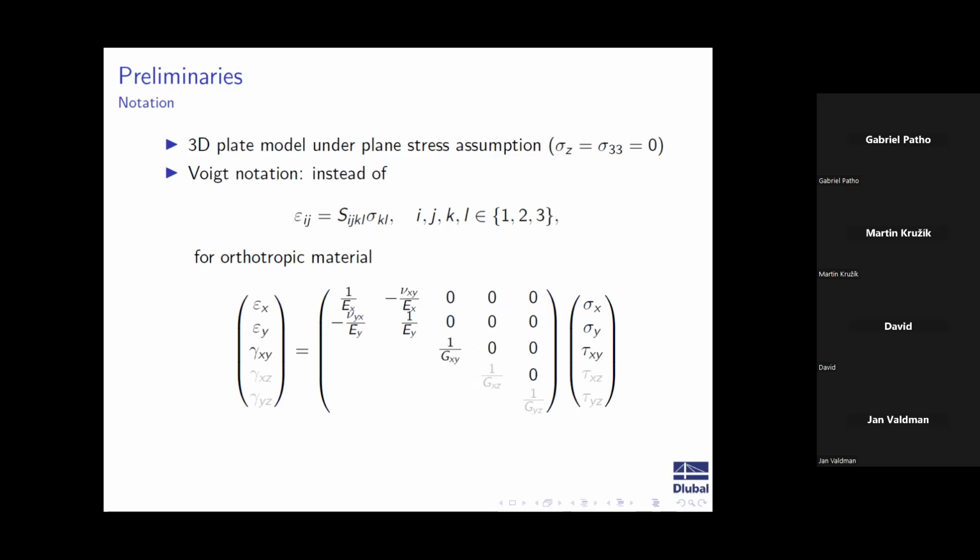So we will for sure need an orthotropic material, which means that we have orthogonal planes of symmetry, which masonry, of course, very nicely fulfills. This is already a step up from basic civil engineering. We do have a symmetric matrix. So although I have written here 2 Poisson ratios, mu xy and mu yx, they are related to each other.